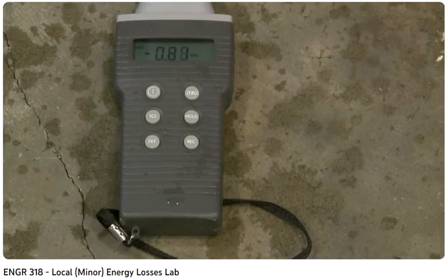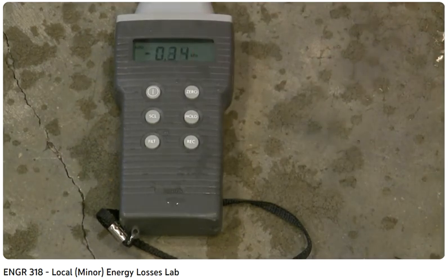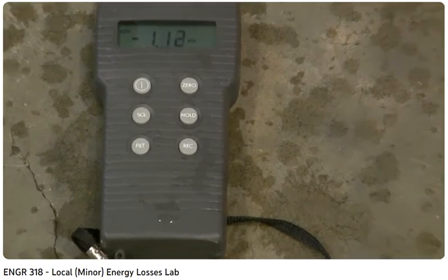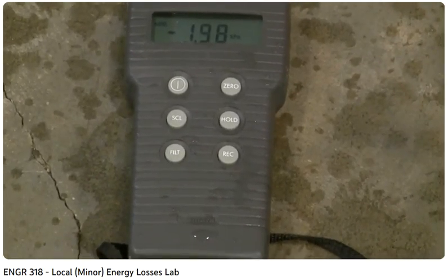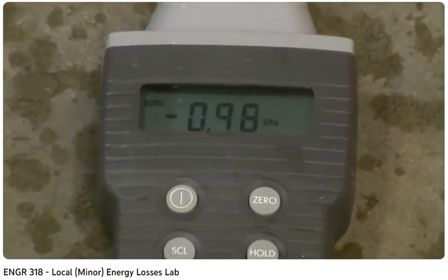Okay, you can see that the pressure gauge is jumping around a little bit. What I need to first do is make sure that that pressure gauge is zeroed. So I'm going to close the downstream valve so that there's no flow going through the pipe. I'm going to push the 0 button so that it's been zeroed. Open that valve back up again. Now, since that valve has just been returned exactly to the same position as before, we can expect the same flow rate. The negative pressure measurement means that there's a pressure loss through the fitting, which is exactly what we'd expect to see: less pressure downstream than there was upstream.